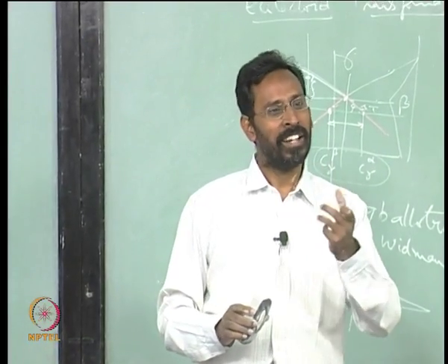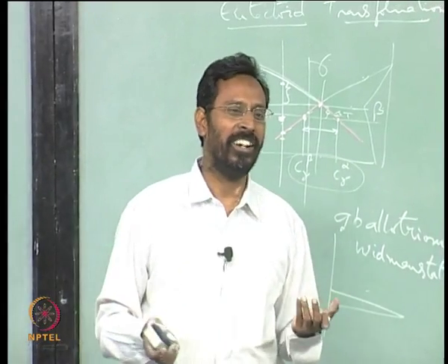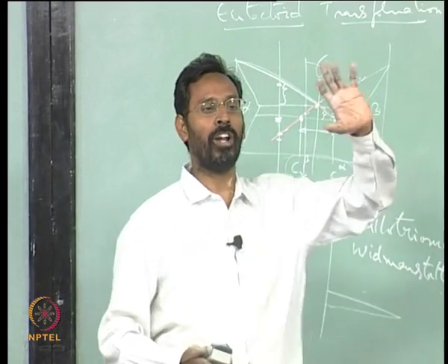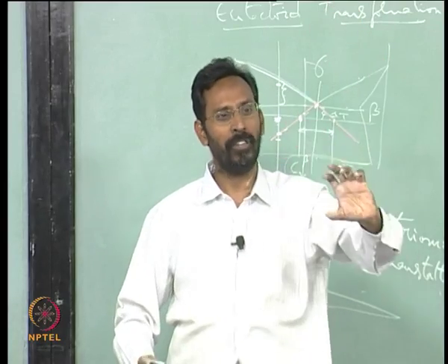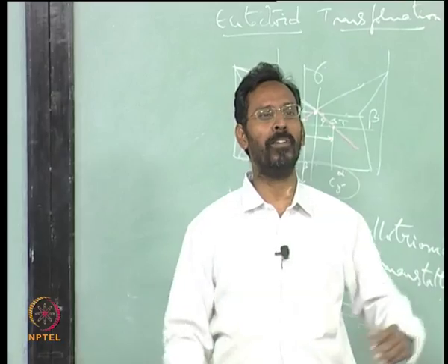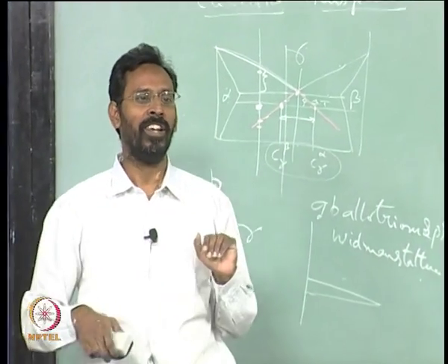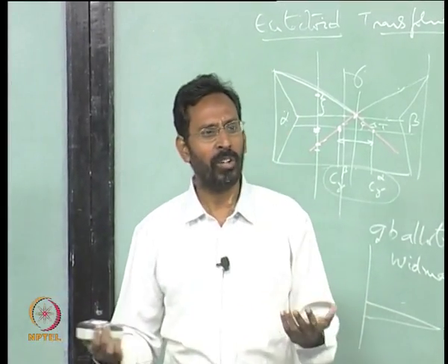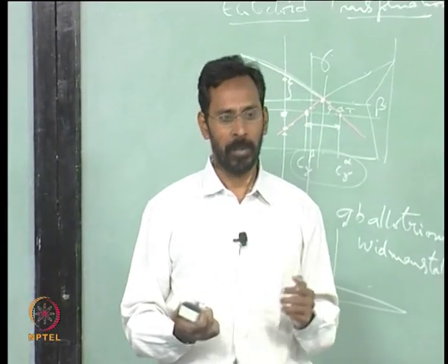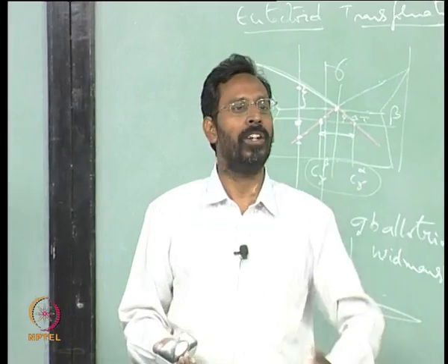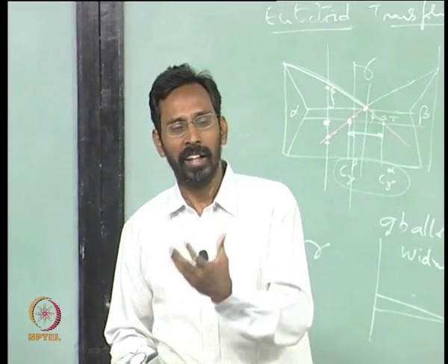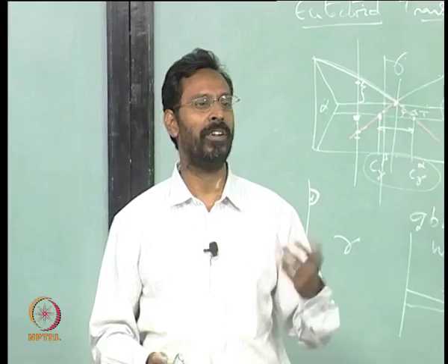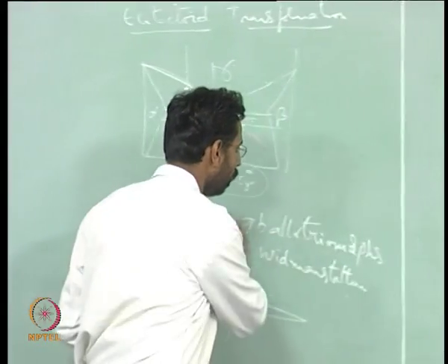So, in principle a bainite can be called a eutectoid, it is only semantics, it is only how you look at it. But if you look at it, the whole transformation is first the gamma giving you alpha of the same composition, which is a polymorphous type of transformation, and from the polymorphous transformed alpha, cementite is precipitating out. That is the actual transformation that is taking place. So, in principle, from that point of view it is not actually eutectoid, but ultimately the mixture is an alpha plus cementite mixture with a different morphology. Okay. Anything else?